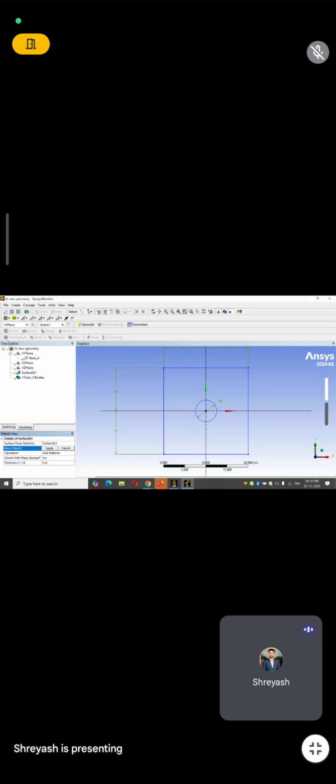So in this, I'll select an object, the sketch that I have prepared. So I'll select sketch one. Okay. If not visible, you can click here. Okay. Click on sketch one. So you can see the yellow color lines. So this all is our sketch one. So if I want to prepare a new sketch, I can do it from here. Okay. New sketch option.